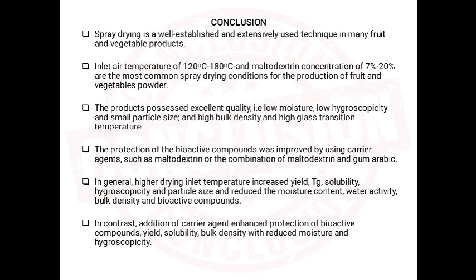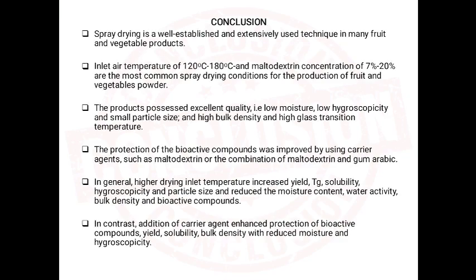In general, higher drying inlet temperature increases yield, glass transition temperature, solubility, hygroscopicity, and particle size, and reduces the moisture content, water activity, bulk density, and bioactive compounds. In contrast, addition of carrier agent enhances protection of bioactive compounds, yield, solubility, and bulk density, with reduced moisture and hygroscopicity.